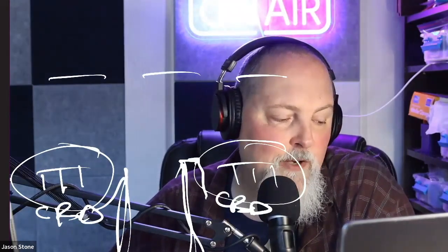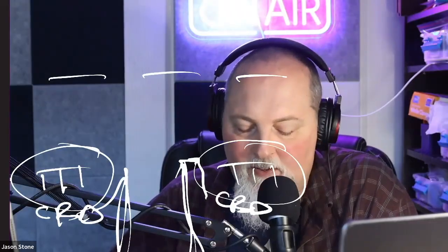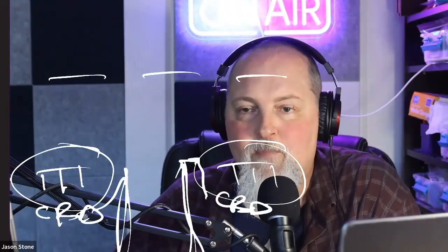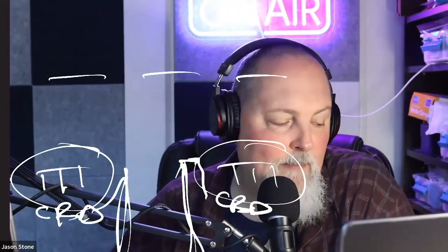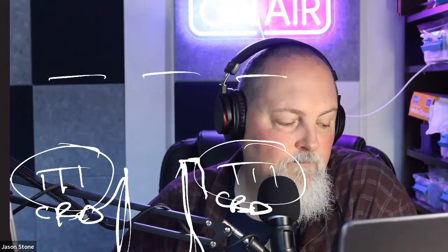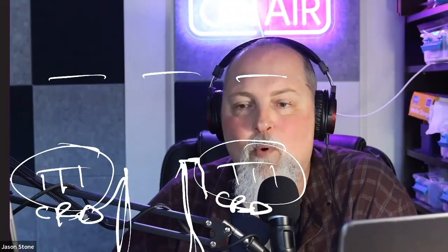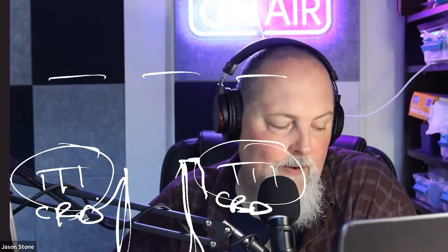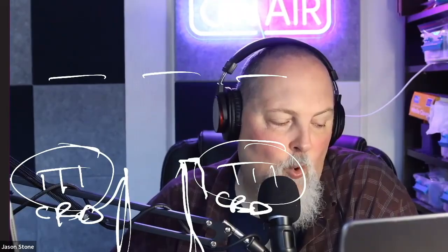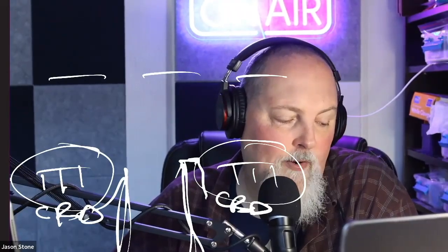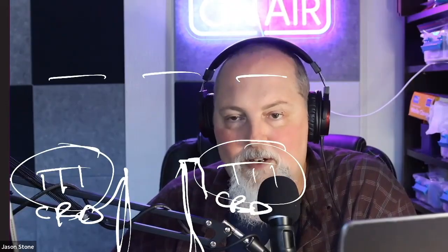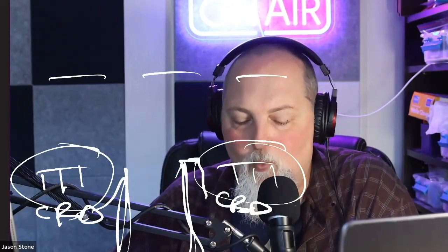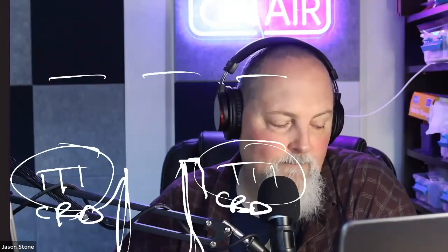Safety equipment's grouped into two or more divisions, physically and electrically. So we have to keep things in different rooms. We have to keep the cabling separated. And that's going to be the important stuff: the emergency diesel generators, core cooling pumps, cooling water, containment isolations, any emergency filtration equipment, that kind of stuff will all have that divisional separation.